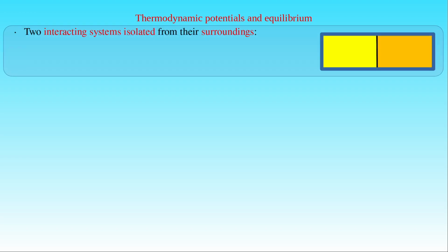We can apply the fundamental equations of thermodynamics to give a quantitative analysis of the conditions for thermodynamic equilibrium. Let us consider a thermodynamic system separated into 2 subsystems with a wall. We assume that the system is isolated from its surroundings with a boundary which is an adiabatic, fixed and impermeable wall preventing the exchange of any heat, momentum for pressure work, and matter. We also assume that no external forces act on the system.